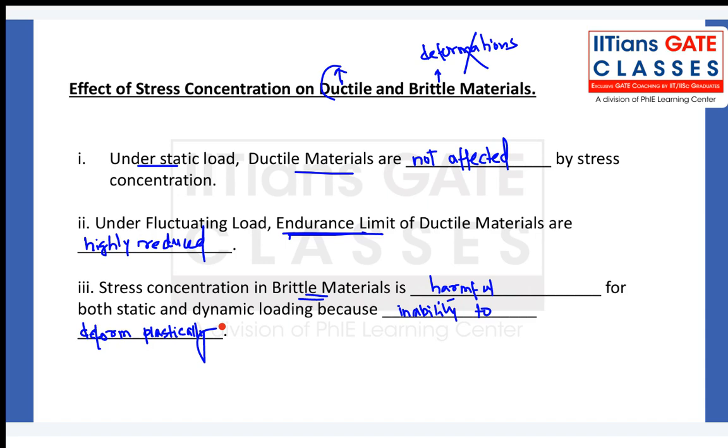So why have we not used stress concentration in static loading? Because generally for machine elements, we mechanical engineers don't use much of brittle materials. Most of the time what we use is ductile materials. We don't use brittle materials. So that is why we have not considered stress concentration for static loading.